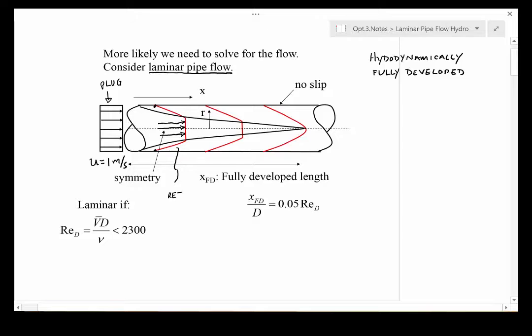You can think about that layer as a boundary layer of sorts. So it's retarded near the wall and accelerating off the wall. So you see that the flat profile changes: there's a region where the wall influences the flow, and in some sense it influences it everywhere because of the acceleration, but there's a place where it retards the flow.